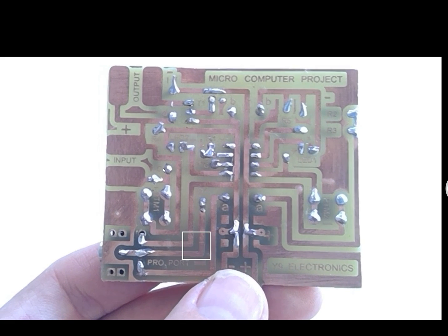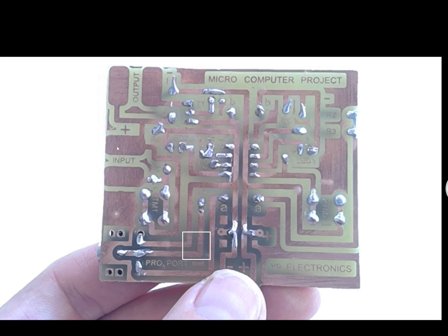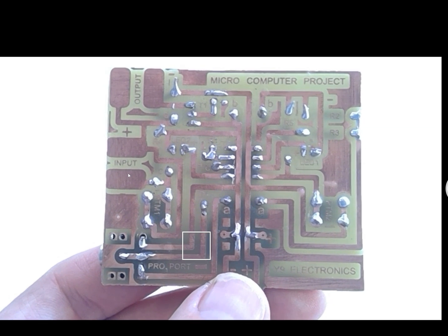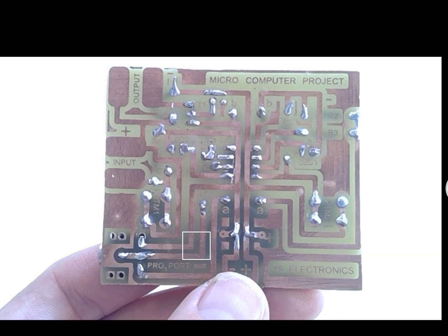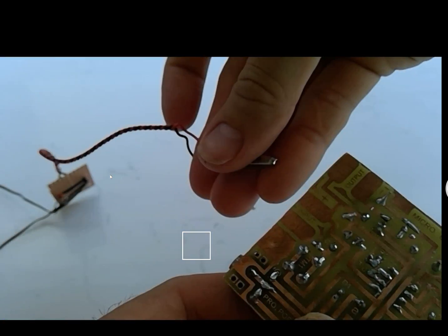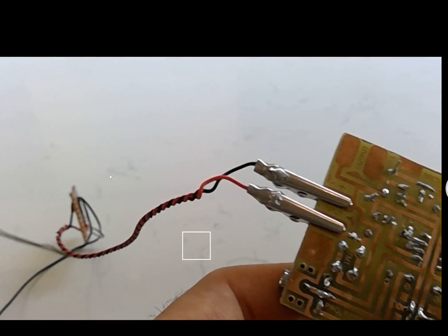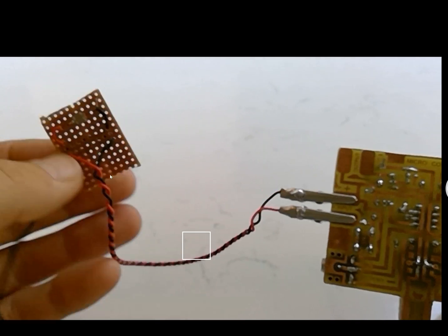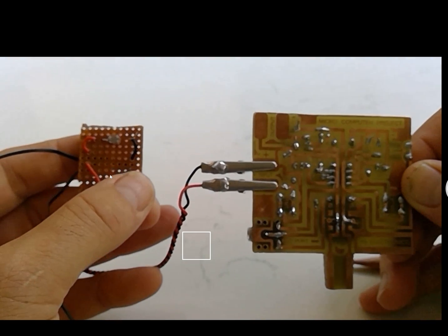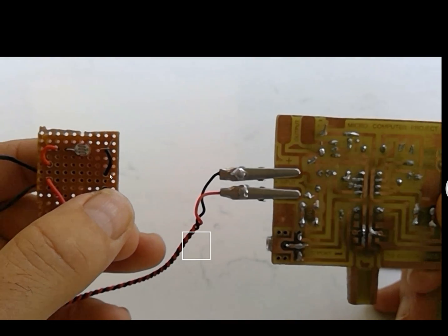But also what's connected to it is this input. Can you see that this is a high, and this pad here is connected to C. Therefore, if I connect something to these input pads, for example, I've got here an LDR, a light dependent resistor, if I have an input component, I can then use my LDR as a switch, but it will have an infinite number of states as opposed to just the on and off state that our push to make has. All right.